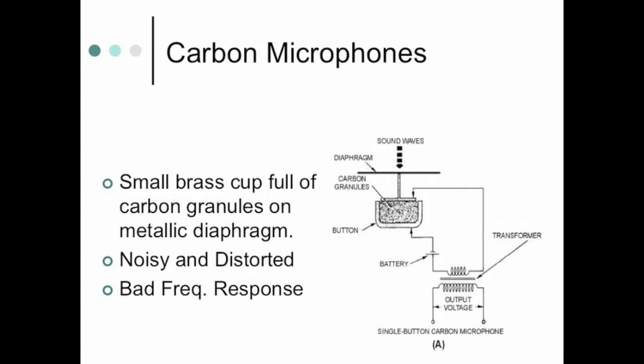They're very crude, but it's a really ingenious way of capturing sound waves, hitting a diaphragm, and making it adjust how much resistance is in this little cup of granules of carbon so that we can detect and sort of encode what the sound wave was into electrical impulse. They're noisy, they get distorted, and they have bad frequency response, but they're extremely durable, which is the good part of what they do. They don't break very often.